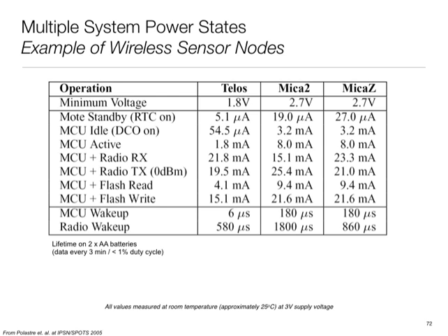And you see a fair bit of diversity emerging there, depending upon whether the designers paid attention. I offered this one because in these early days, for wake up, you see 6 microseconds versus 180 microseconds, quite significant differences. And even now, by the time you look at the combination of processor and operating system and all, you may have vastly distinct things. I guess what I'm trying to point out is that if you care about power, if you are in a setting where you're duty cycling, these are numbers you need to look at. These are not the headline numbers.